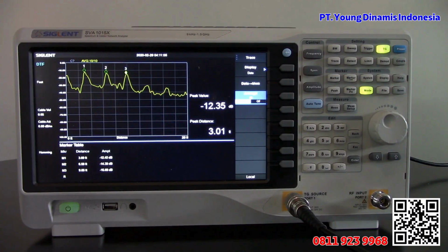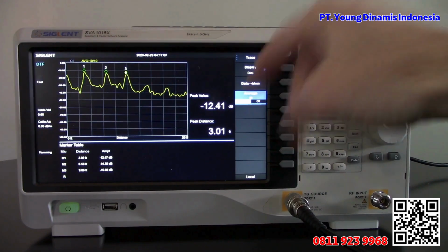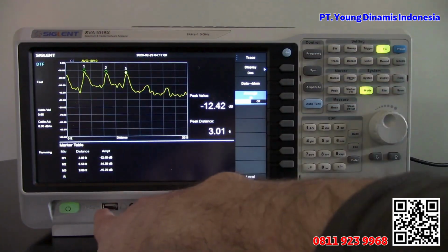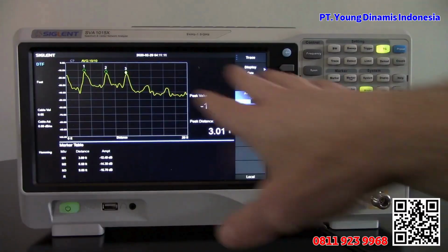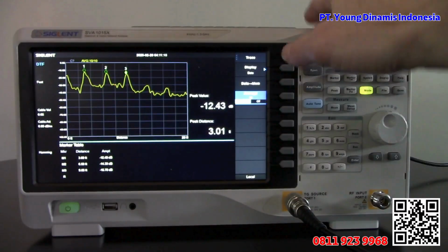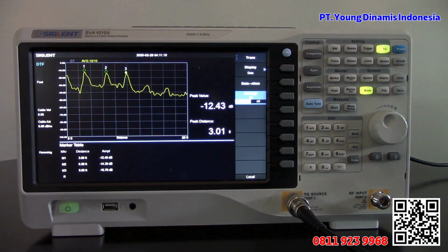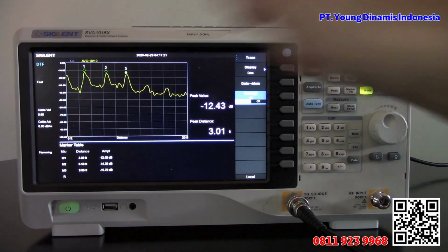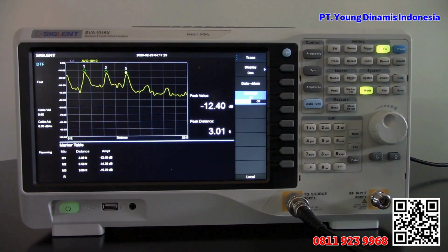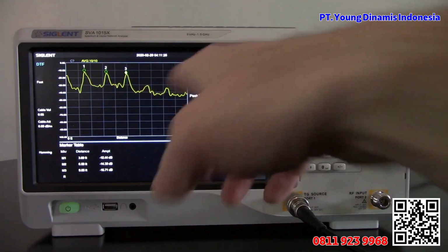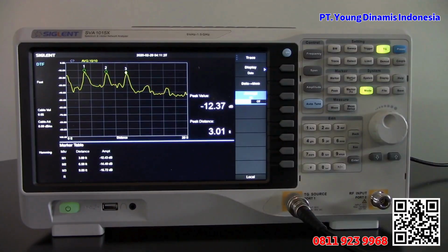We can see each one of those connection points, and we could actually take a picture of this if we wanted to. We could insert a USB stick and save this picture exactly as it stands, or we could save it to memory and compare it later. So as the connections may degrade over time, we can compare the new picture to this existing picture. So as your cables age, you can start to see whether it is corroding in certain areas.